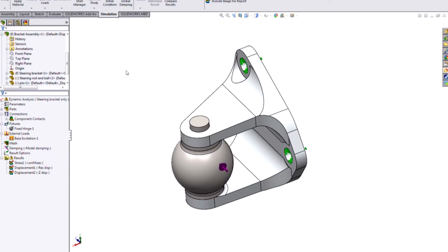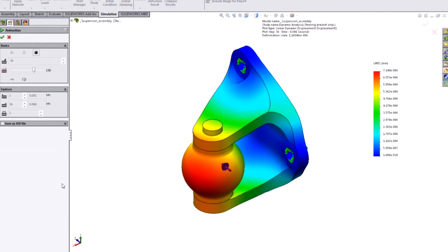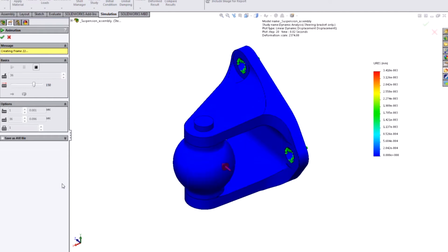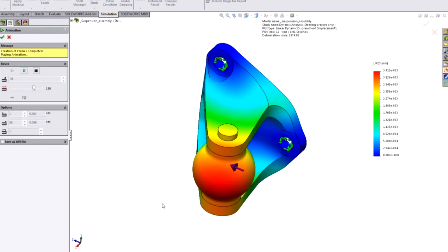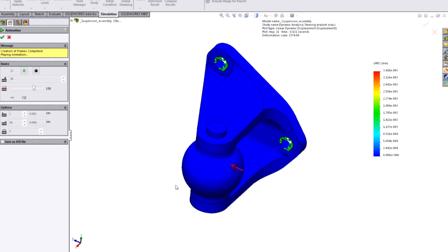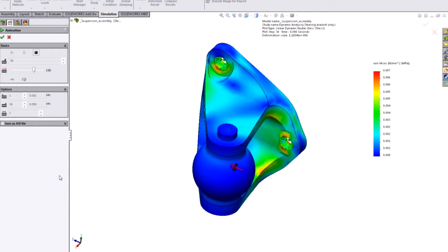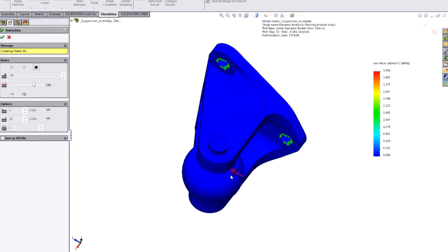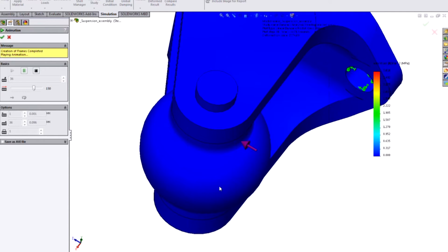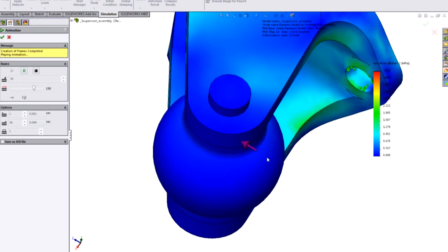So we've now got a dynamic load and dynamic input. When we solve that, because we're talking about dynamics, we don't just have a stress picture, we almost have a stress video that we can look at. Now this object's pretty stiff, so what you see is the input moves with the shock, and if you look closely, you'll see it vibrating afterwards as those vibrations damp out.